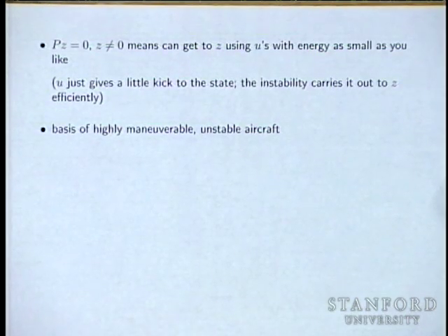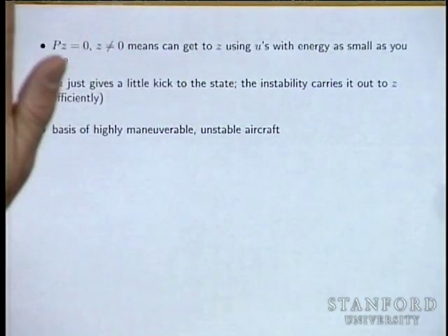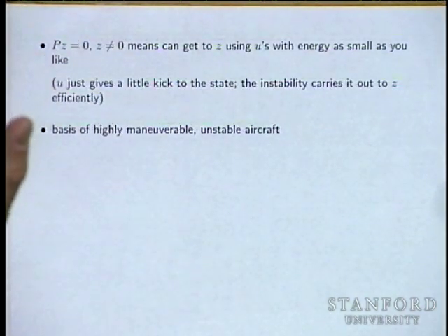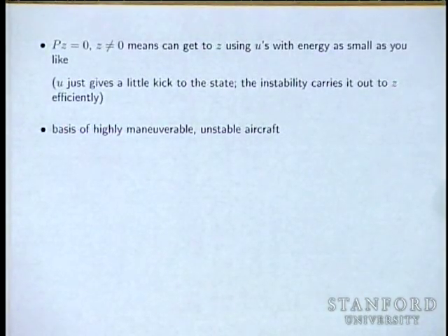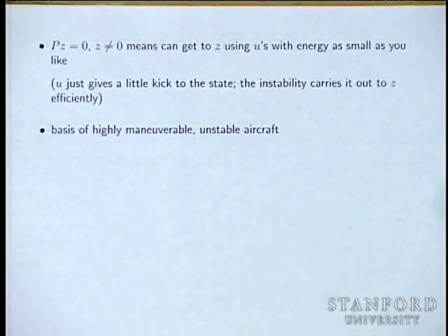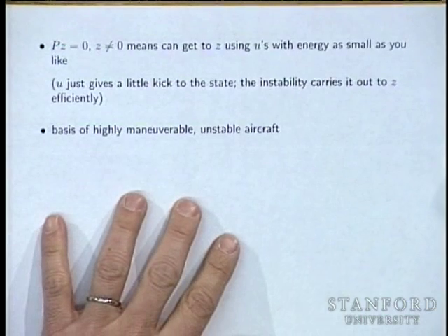So let's think about what this means. It means things like your nose goes up, and instead of there being a force or moment that pushes your nose down, when your nose goes up, actually there's an up torque and your nose goes up faster. I remember I know the eigenvalues on some of these things. Some of them are on the order of about 1 in the continuous time case. So that's e to the t. So basically your nose goes up in about 1 second, it's about a factor e higher. In 2 seconds, it's 9. And so someone even explained to me how they work.